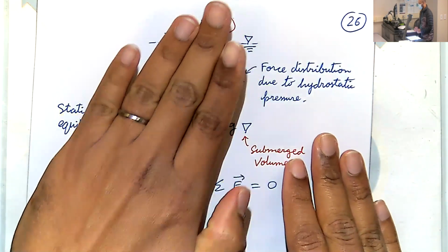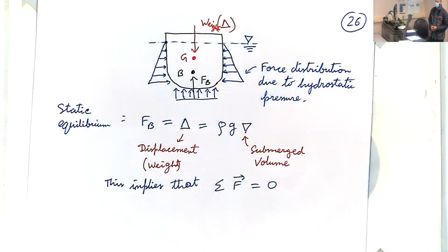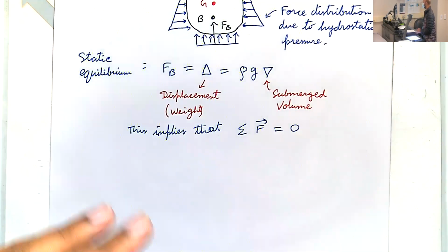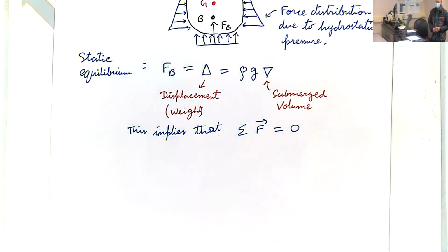And we'll see exactly how much it will tilt. How do I make sure it doesn't tilt over all the way? All right. And we'll use all of the things we've talked about. The area moment of inertia is useful for computing that. The centroid, the center of buoyancy, all of these we need to know to be able to compute those things.